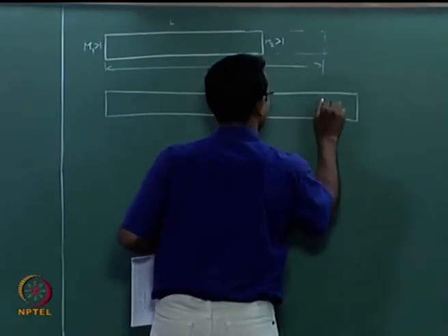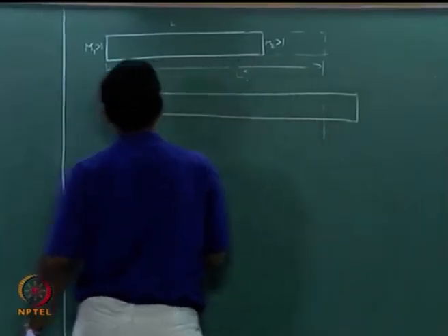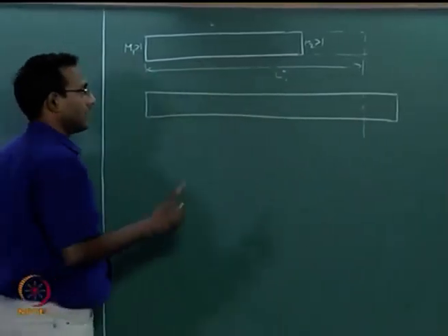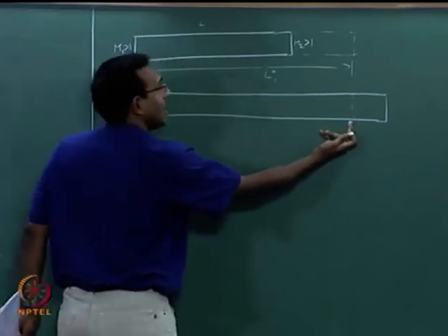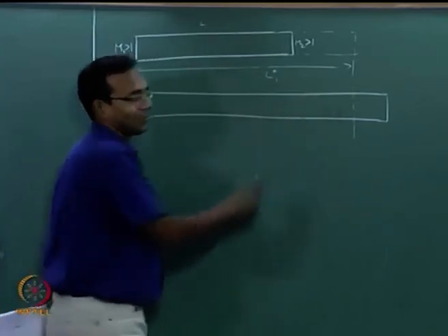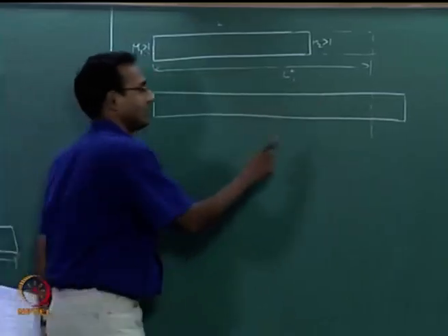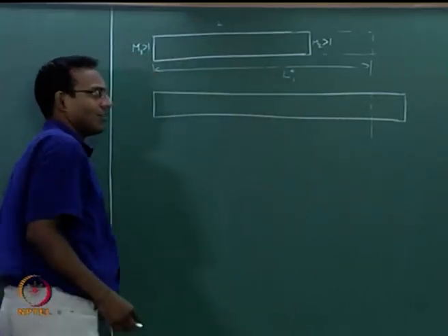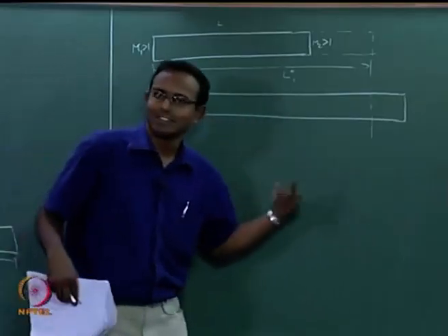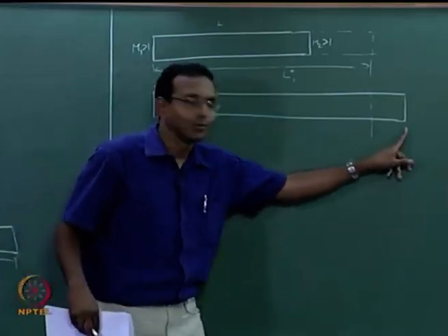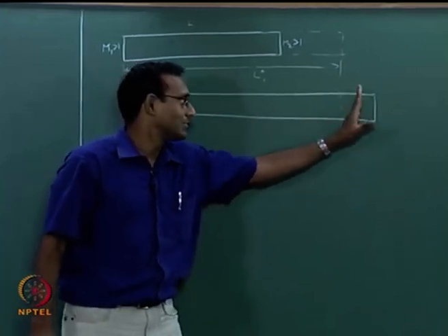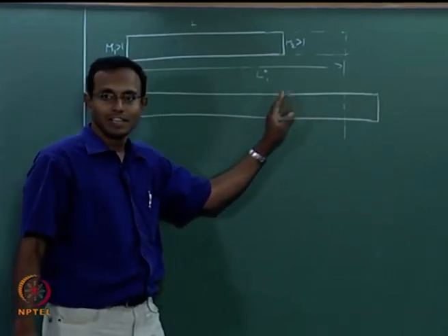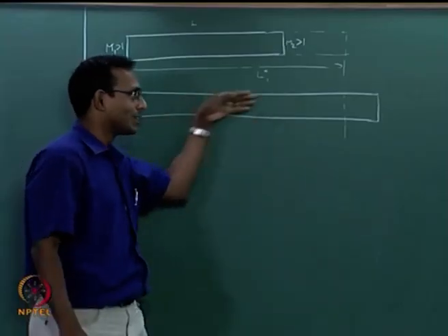Say I am just slightly more than that L star case. If I have this case, then typically there will be a shock. By the way, it will be ahead of this L1 star location. The shock will always be ahead of this. What is the rationale for that? This extra length is what is going to cause excess resistance, and so that will send out a set of compression waves, and as they come in, they find higher and higher Mach number flow resisting it.